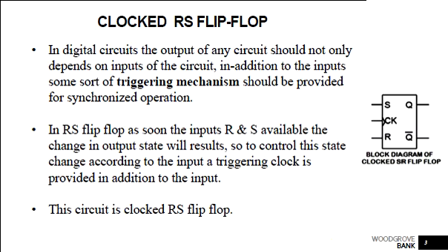Now, in a digital circuit, the output should not depend only on the input. In the last slide, we discussed the RS flip-flop, where the output depends entirely on whatever data is given to the input. But in addition, there should be a triggering mechanism so that we can have synchronized operation of the system.